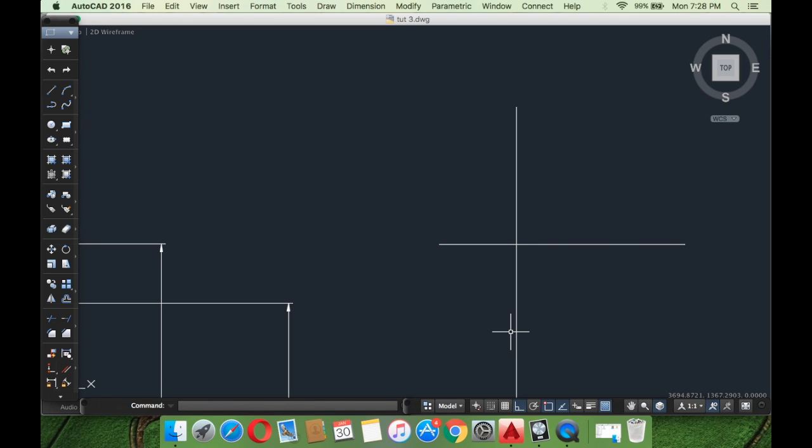Now let me tell you, trim actually works in a much easier method. Before we go to that, let me clear out the simple method, then I'll go to the tough parts, or the shortcuts. So I select trim from over here. It asks me to select the object, suppose this one, then I press enter, and then I simply cut it there.